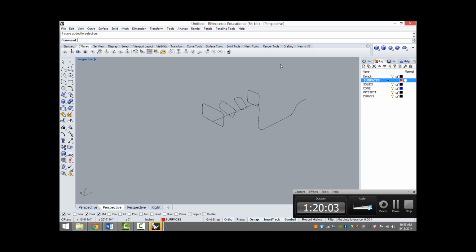Yeah, so sweep is only a surface command, but you can either extrude the surface afterwards, or you could offset the surface with a cap, or you could thin the surface. There are a lot of different ways of giving material thickness, but that's a really good question.